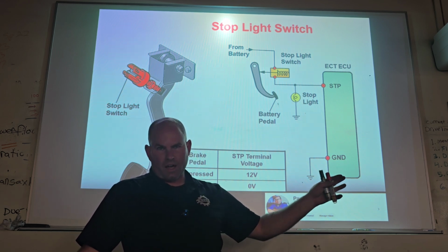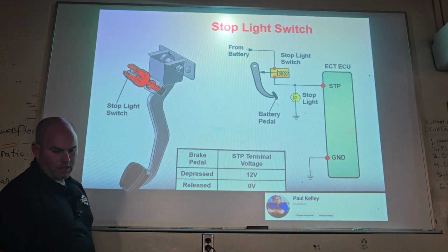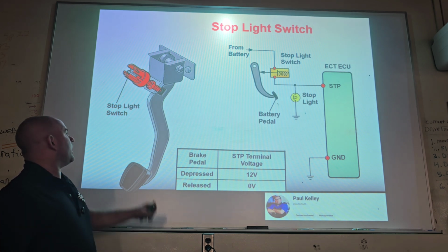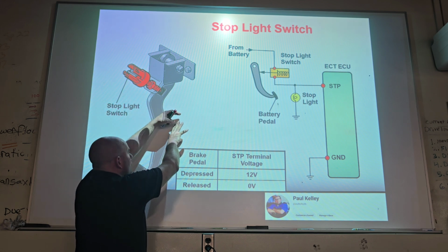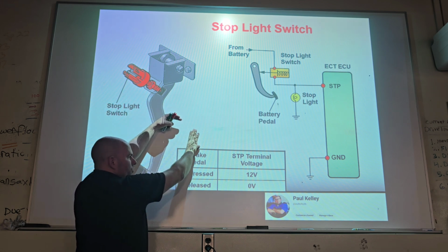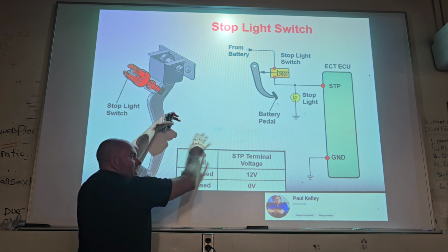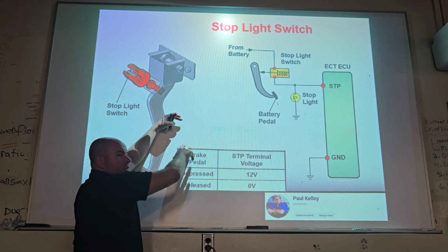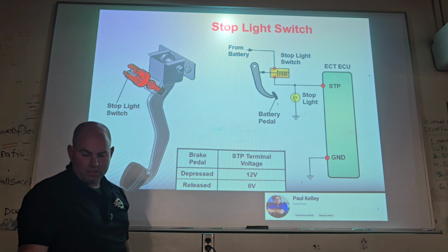All those systems rely on that, okay? And it could even be just a loose adjustment. A lot of times if this thing's backed off, it'll actually show it on all the time. And if it's so far down, you'll actually have to push the brakes really low. So the customer may just be tapping the brakes and it's not actually closing the circuit. So consider the adjustment a little bit too.